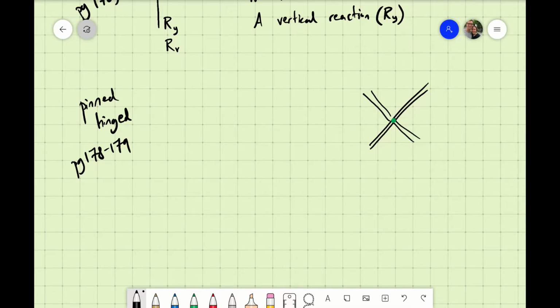So the pinned support, when something is stuck to the ground, and this is just like the diagram in the book. It's when you've got an object that really is truly literally hinged, pinned, just like that. It might be the middle of a seesaw, it might be the end of a bridge, like I just said. It could be a link in a machine. It could be like a steering link in my kids' little go-kart that they love to push around. Really, it's very, very common. Things that can rotate, but that's all they can do.